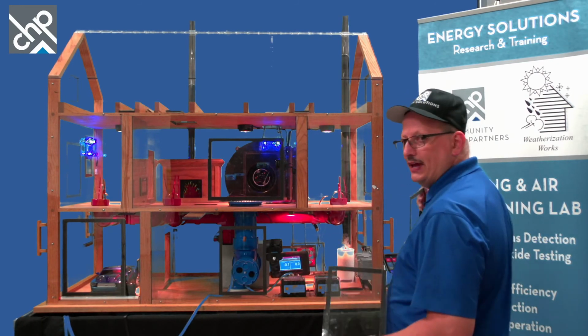And sometimes that's what I'll do. If I'm at a house and I got a negative pressure issue and it's backdrafting, and just to confirm that it's a pressure issue, I can open up a door or a window to that CAZ and it should relieve the pressure. And if I relieve the pressure, then the smoke should go out the chimney. If the smoke still doesn't go out the chimney and I've basically relieved or neutralized the pressure, then it's probably got something to do with the chimney itself. It might be a blocked chimney or something like that, as far as past failing spillage.